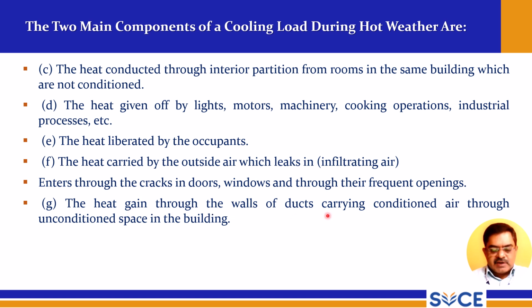through the walls of ducts carrying conditioned air through unconditioned space in the building. Even the ducts which carry the air conditioned air will transfer heat through conduction from the higher temperature to the lower temperature, that is inside the duct. Then the heat gain from fan work: when fans are operated there will be heat gain, and that becomes a load to the air conditioning system, and it can be minimized or reduced.